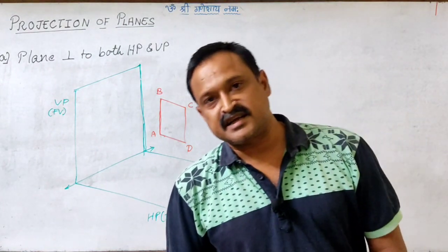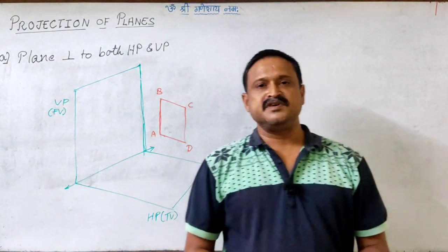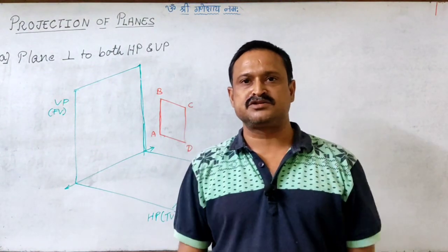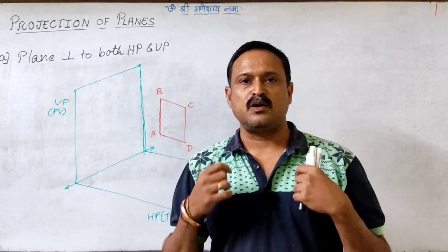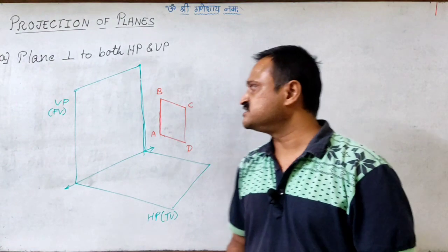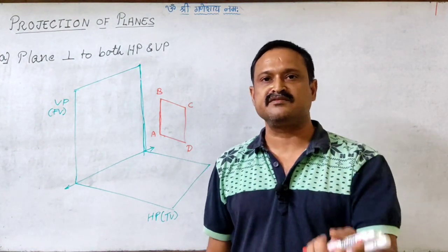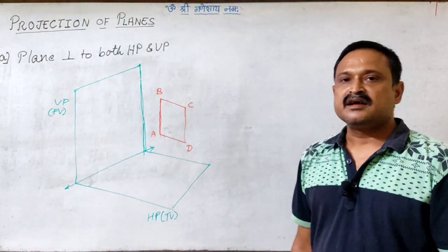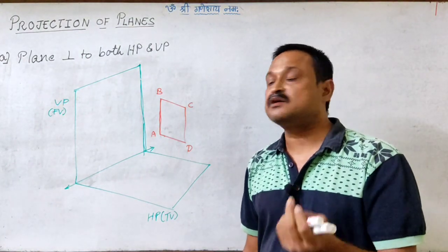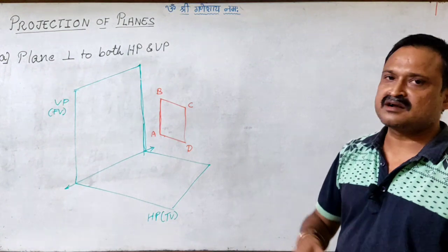When I wanted to project a line, what we did is we projected any 2 points of that line on the required principal planes, and simply joined those 2 images of the points and we got the required image of the line. So same fundamental will be here.